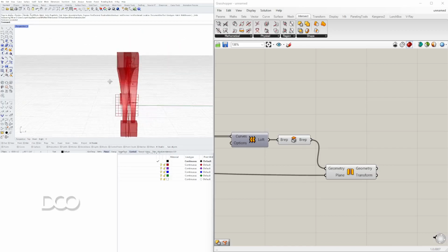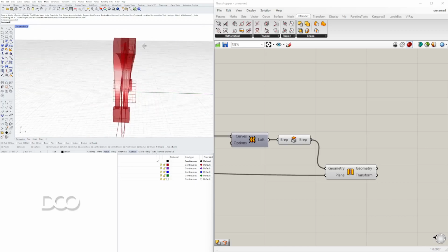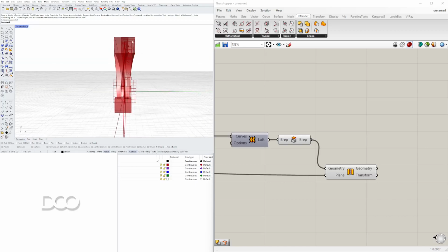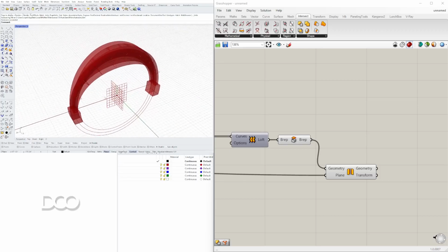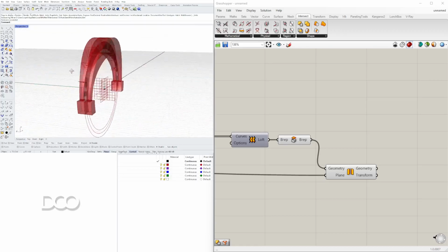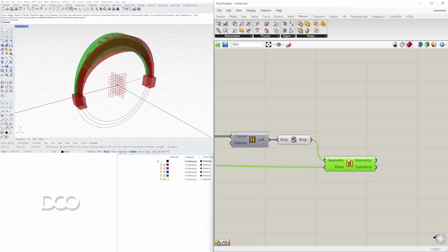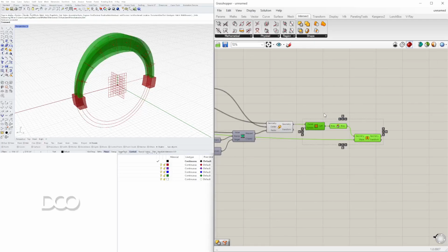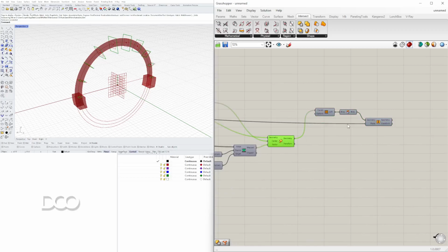And I feel like that looks really cool, but the last thing we'll be doing is taking this geometry, and rather than it just scaling down here, we're actually going to be moving all of this to the right and create some kind of shade structure. So like when you're standing under this, you should be able to be covered. So let's go over those steps. What we'll do is disable the preview on this, which is going to be all the loft and the mirror plane, because we need to recreate that loft.